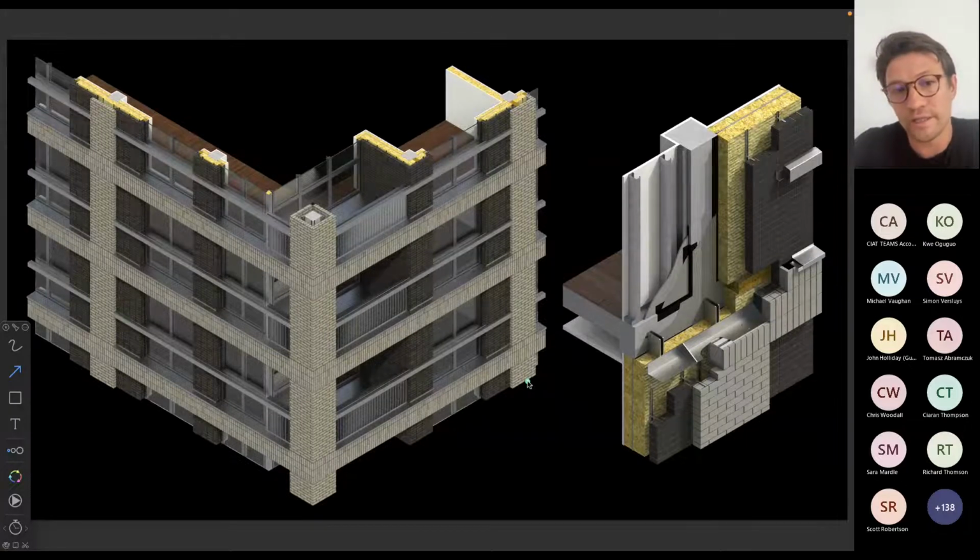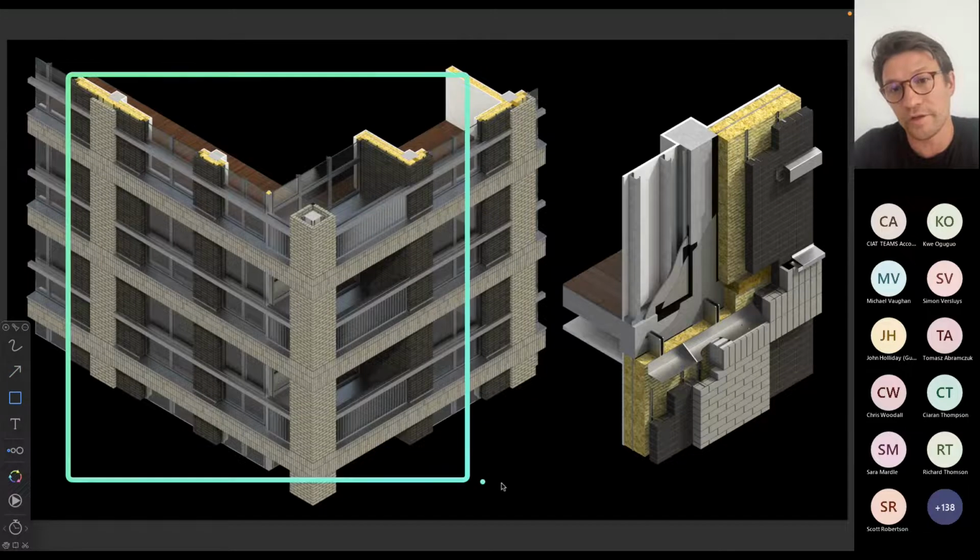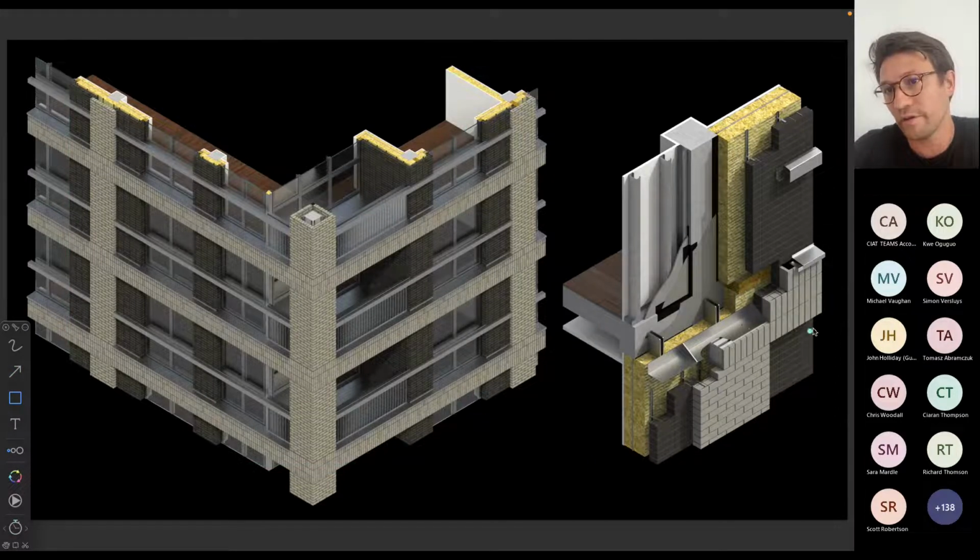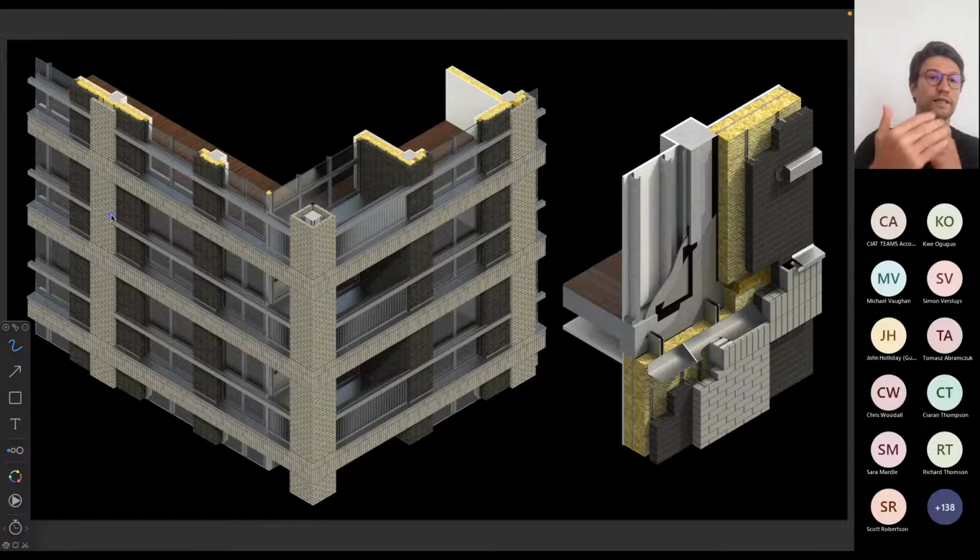This building, this outlook over here, could be achieved with the masonry veneer, with the shelf angle. However, the shelf angle will have to be installed at every floor, not at every other floor or as we've seen before on the very bottom of the building, because of the complex pattern where the bricks are recessed in and out.